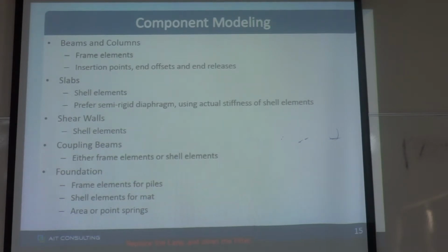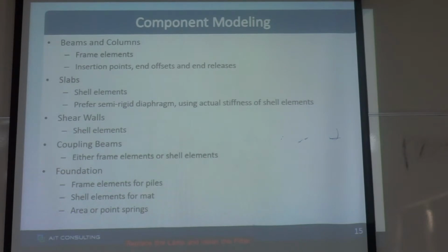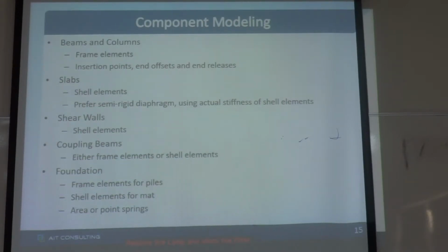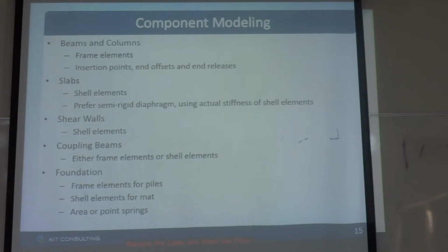And for the foundation modeling, if your foundation is a pile foundation, we normally model the piles as frame elements, and we model the entire length of the pile, and we apply lateral sway springs on the pile to model the interaction effect of the sway. If we model the pile, we can check the forces in the pile and also do the design of the piles directly from the program.